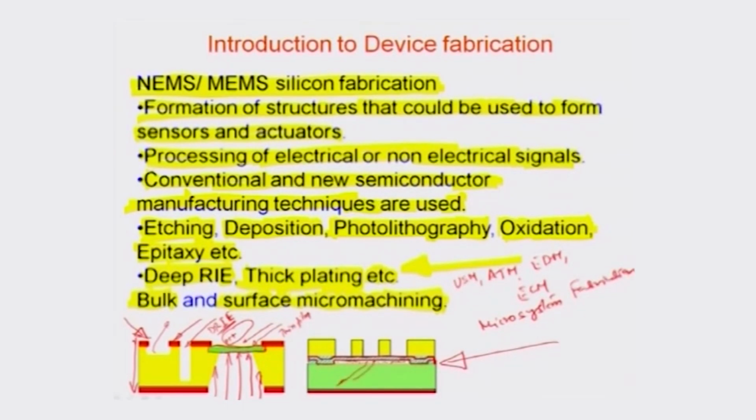So, you can remove away this resist, later on it just goes off, thus resulting in this channel into the plane of the paper or plane of this transparency slide. So, this is an example of surface micromachining or additive micromachining.